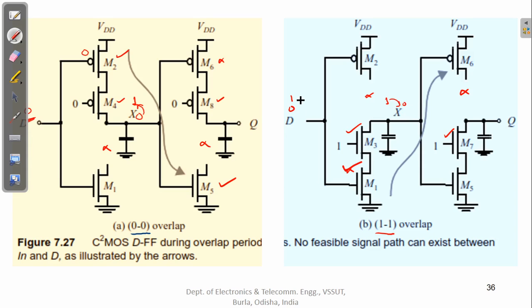Now if X is changing its value to 0, that will make this on and this off. So this is the scene for this output node, that this is again disconnected from the high or the low logic. So under this change in X, Q is still able to maintain its previous value. So Q will still be Q(t-1).